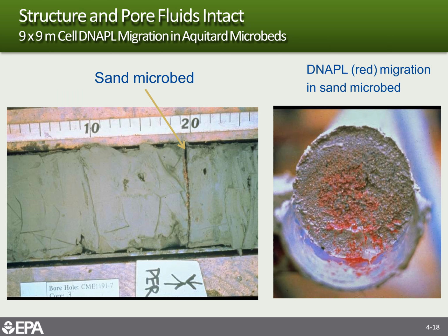Here in this particular case, in the middle of this fairly thick clay, I believe that's centimeters at the top, you'll see that there is a little tiny sand zone, and that sand zone was treated with a dye that turns red when there's DNAPL present. So in the middle of that big fat clay is a little zone of DNAPL. You would have missed this if you hadn't had a continuous core.